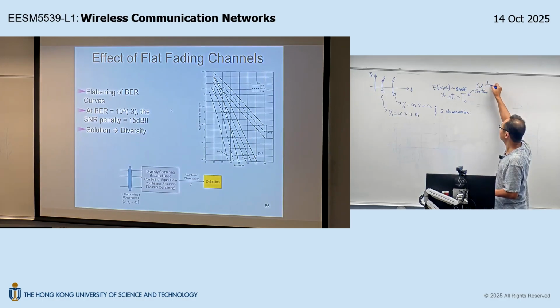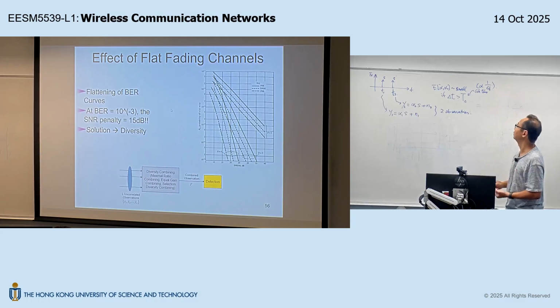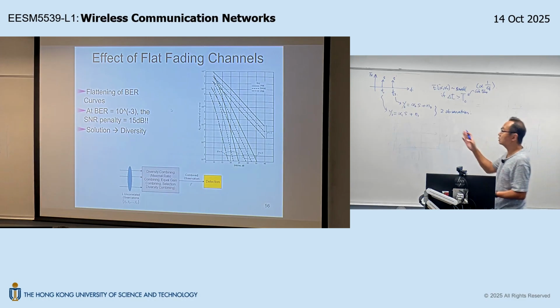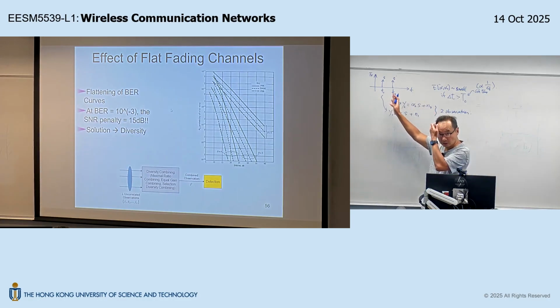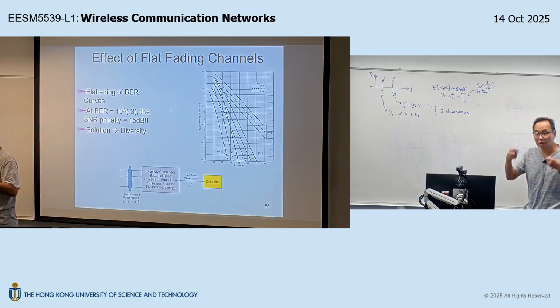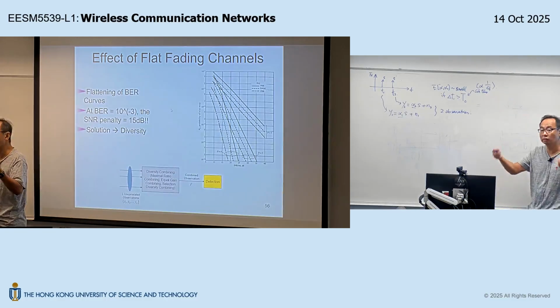It's inversely proportional to the Doppler spread. Remember that? So we just need to make sure that in this scheme, I separate the 2 times of transmission sufficiently for these 2 fading coefficients to be independent from each other. So then I would get 2 distinct, uncorrelated chances of transmitting my symbol.